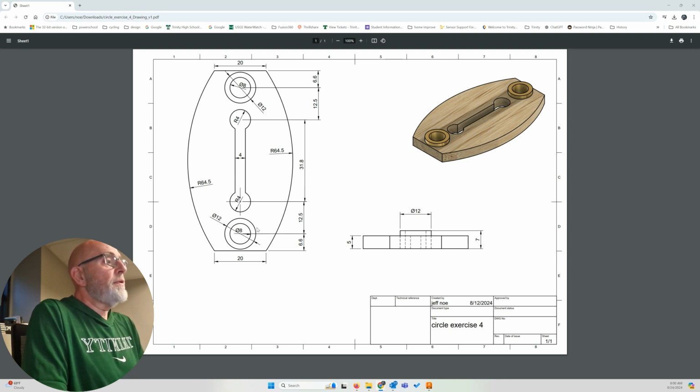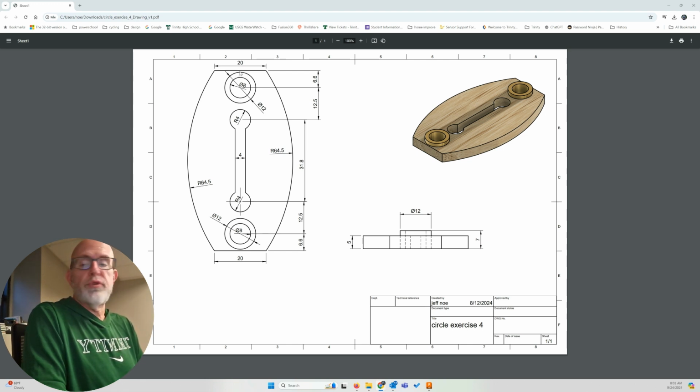I'll create either a 12 millimeter or 8 millimeter center diameter circle. I'll position that circle 6.6 millimeters from the, I'll create it on the line, the vertical line we drew here, that is at the midpoints, not on the axis.